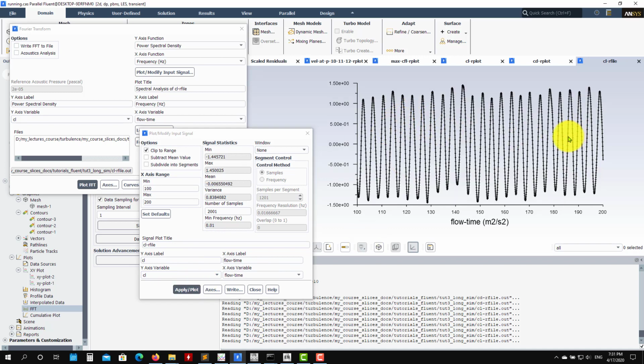Okay, so see that probably here is better, but the idea here is to be careful when you are doing the sampling. Just don't look only at one signal, look at all signals that you have, like drag coefficient, put many sampling plots, sampling the solution there, and see what is going on. Okay, sometimes it can be really misleading.